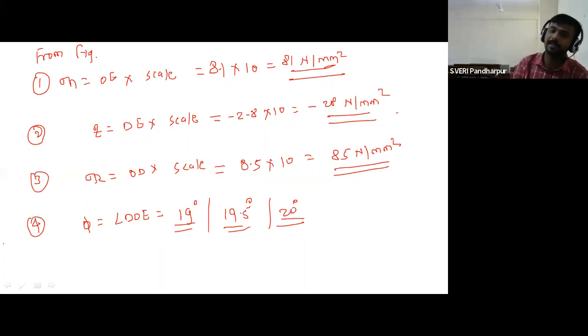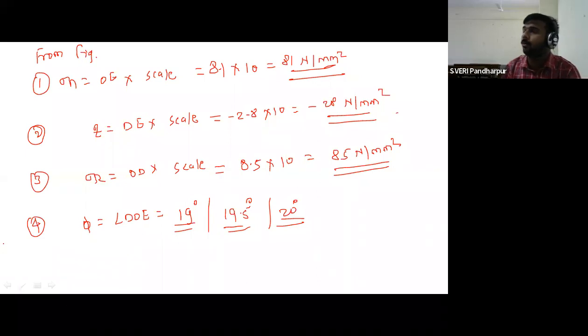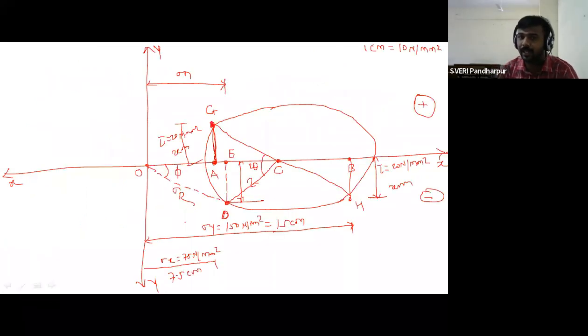But in case number 3, we have to represent the shear stress also from points A and B. Then we are drawing the inclined line. Due to that inclined line, you will get point C. And by selecting the inclined radius, we are drawing the circle.